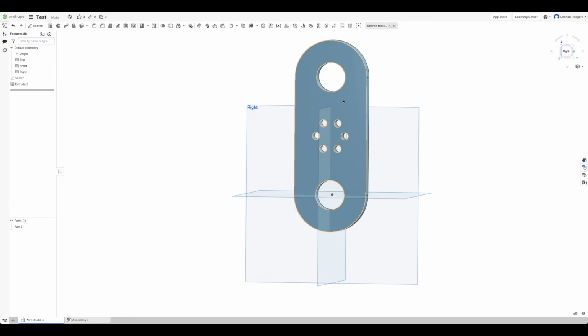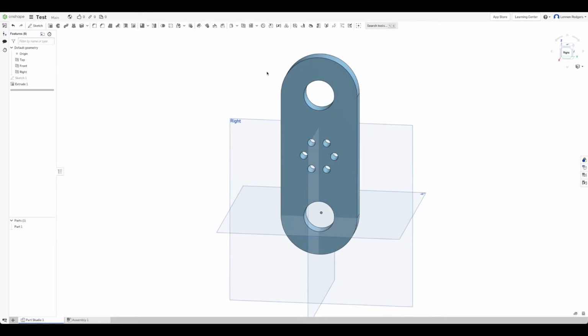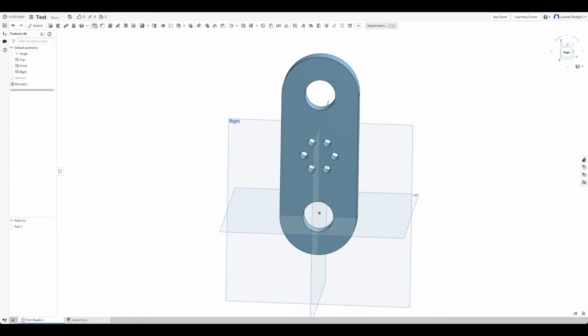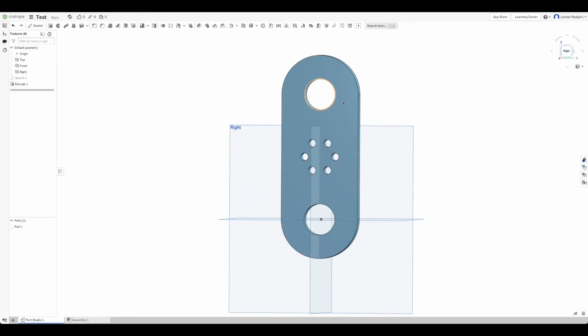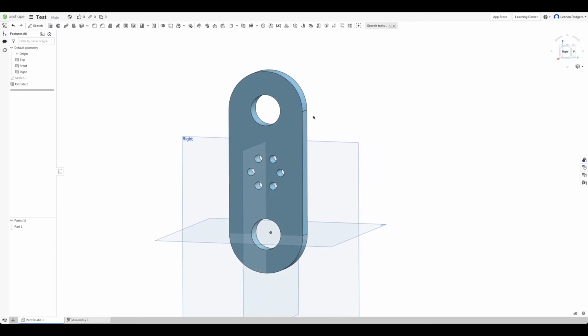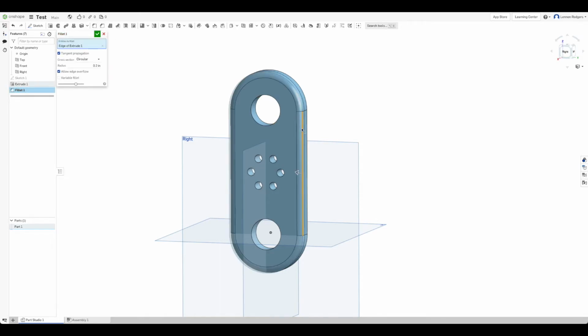So just as another example of the many different features and tricks you can use within sketches, another feature you can do is to create things called fillets, chamfers, and things like that. So I'll show you how you could do that, and that would be if you want to round off these edges. So you can come over here, click fillet, and then there's a lot of different options.